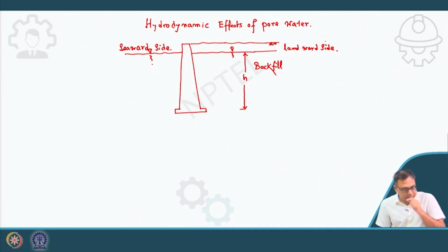Now, for the seaward side, when the water table is not in the backfill, first we will discuss the hydrodynamic force that will act during an earthquake if water is present. Suppose there is a seawater side, so water is present; how much force will act on the retaining wall due to the presence of this water? We will calculate that first. That force is called the hydrodynamic force.